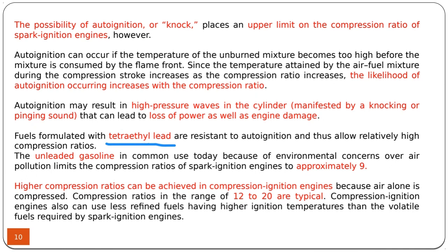Then, because of the environmental effects of the lead, it's not used anymore. Instead, some other additives are used inside the fuel, such as some kinds of alcohols, ethyl alcohol or methyl alcohol. Ethyl alcohol and methyl alcohol also delay the auto ignition, and it can be possible to obtain higher compression ratios by putting some additives inside the gasoline.